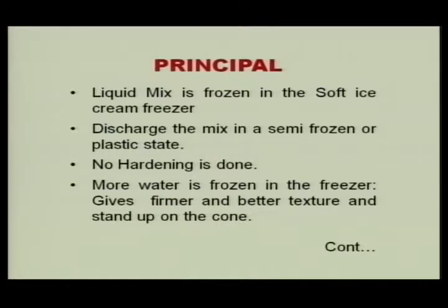This is the product. Now, when we say no hardening is done, if you recall the principle, the remaining hardening is done in the ice cream in the hardening chamber, but in this case no hardening is required. What we want is that the maximum amount of water should be frozen in the freezer itself, because this will give us the firmer and better texture and stand up properties in the softy cone.